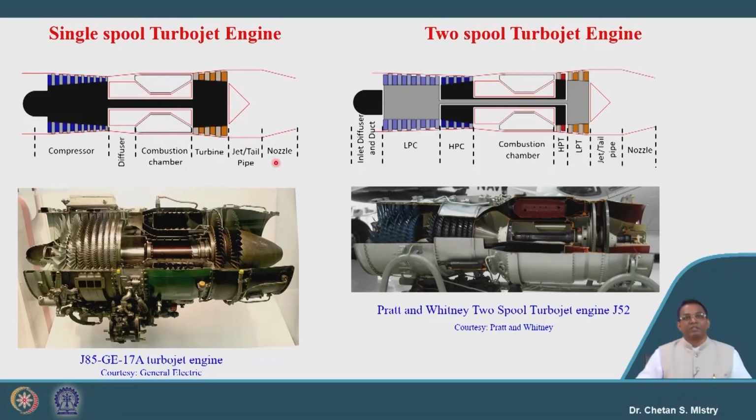As we discussed before, during the Second World War people were more interested in flying high at high speed, but the purpose was for fighter aircraft. Later on they realized they could use this for transportation, where they are looking to carry more weight, and that is the reason why the thrust requirement increased. With the increase of the thrust requirement, we realized we can improve thrust by increasing the pressure ratio and turbine entry temperature, and that gave the indication to add more components.